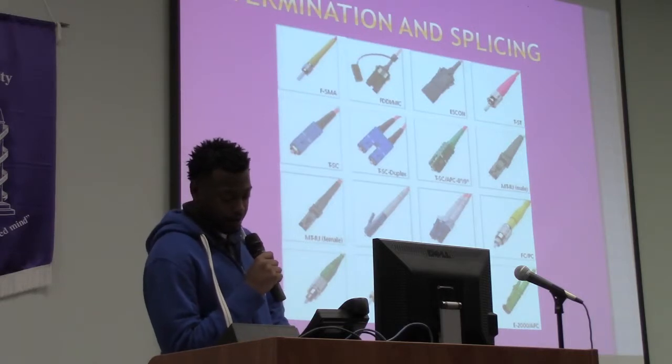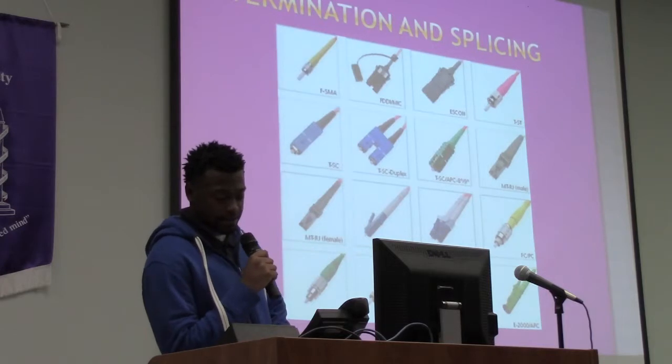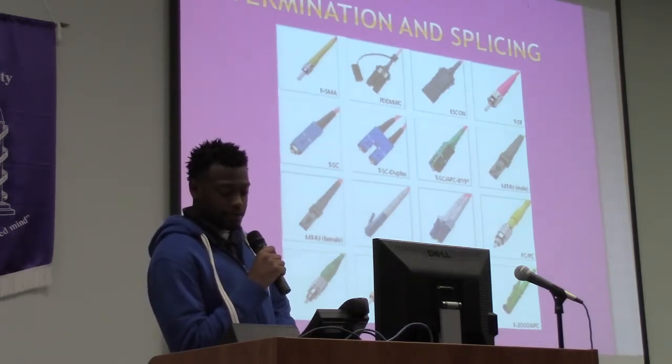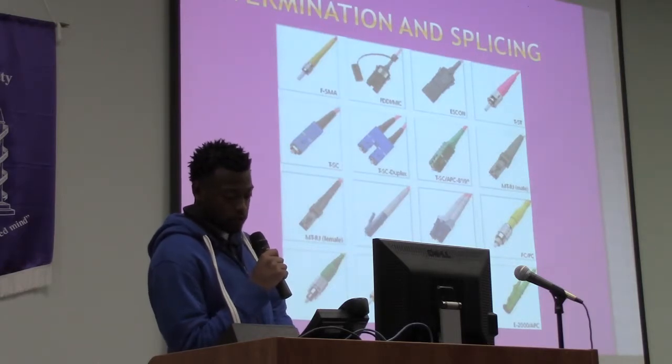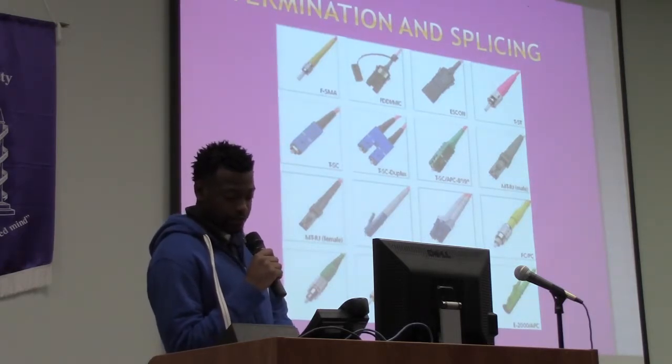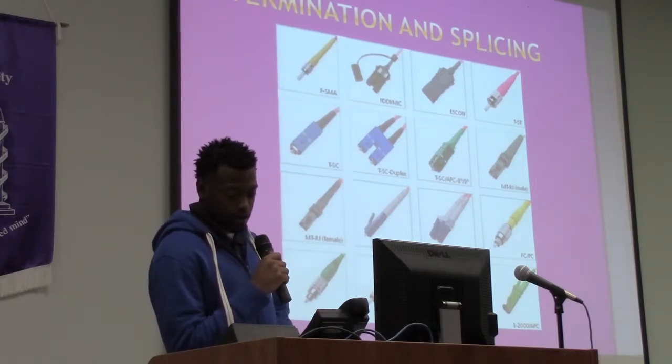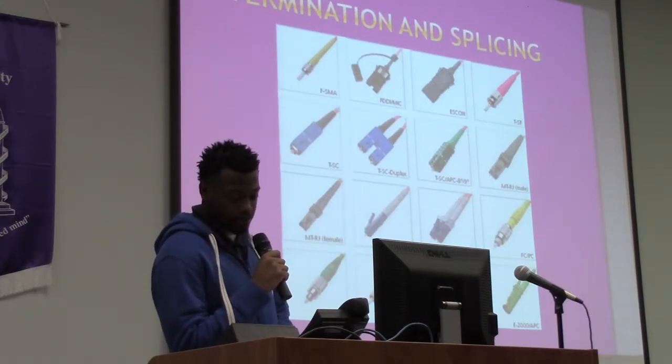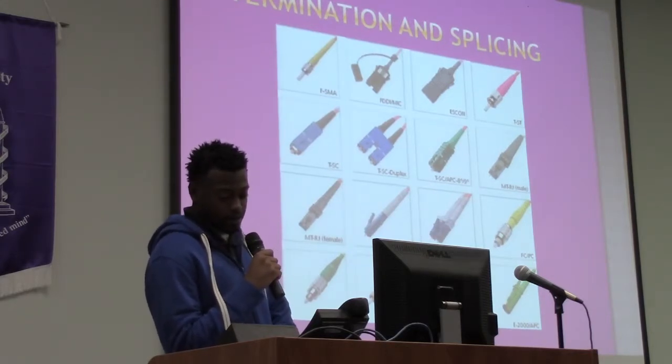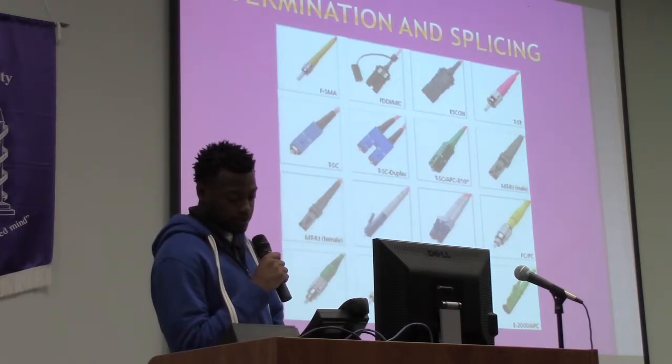And here we have the connectors, which are usually the standard types, such as the FC, SC, ST, LC, MTRJ, and SMA, which is designated for higher power transmissions. All of these standardized connectors are physical contact type, where the mating surfaces touch each other to achieve the lowest possible attenuation, and all but the ST have a keyed ferrule that allows an angled mating surface to reduce reflections that can cause problems with laser transmitters.